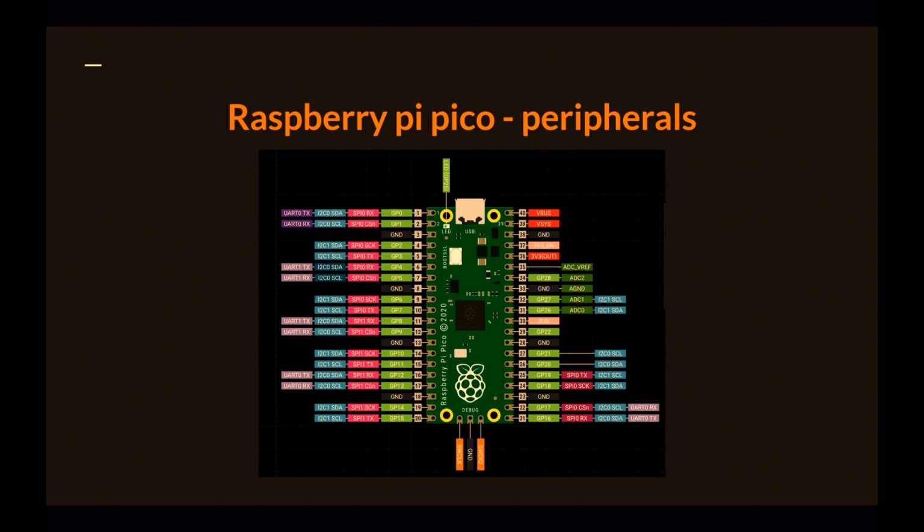It has 40 pins exposed, and if you've never worked with microcontrollers, each pin can execute particular functions. The most popular function is GPIO, general purpose input-output, shown as green text. Some pins also support different functions like ADC, SPI, I2C, UART. You can look at the pinout of your microcontroller and easily understand what pins you can use for what purpose.